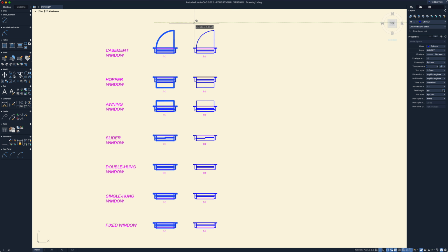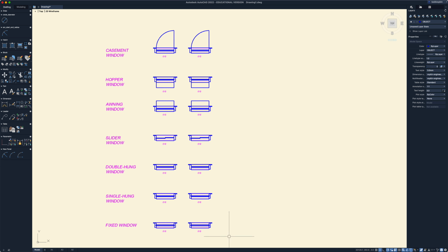slide them over, give it some dimensions, such as, I don't know, 1200 millimeters over, something like that. And now we want to use a stretch command. So STR, which is stretch, and let's try that again. STR. Why are you not working? STR, enter. Okay, and what you want to do is go up and grab that much of the window right there.